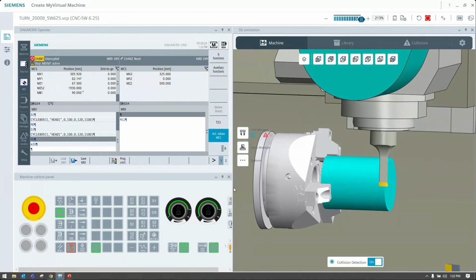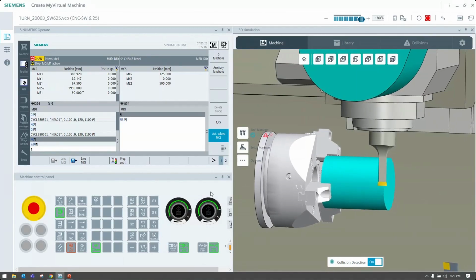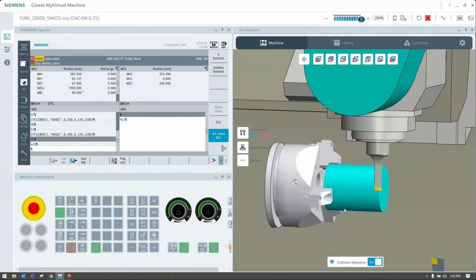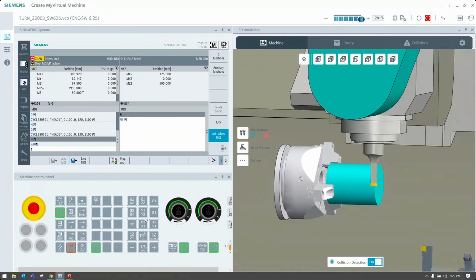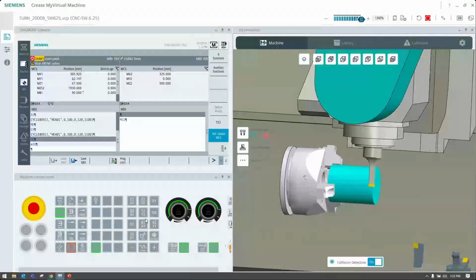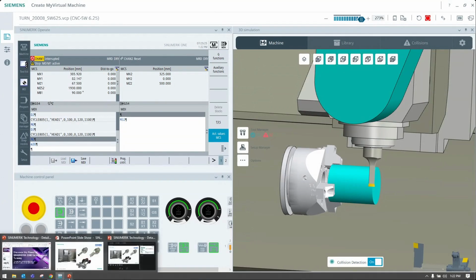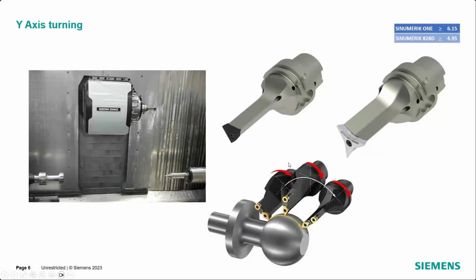Yeah, and we were playing around with it just recently when we had Claudio here, and it could be double the chip load. It's unbelievable. But to your point, it's a force thing, right? We're directing the forces directly up into the spindle bearings, so we have an axial load as opposed to a radial load. And anybody who knows anything about a spindle bearing knows you can drill a lot more aggressively than you could mill, right? Absolutely.